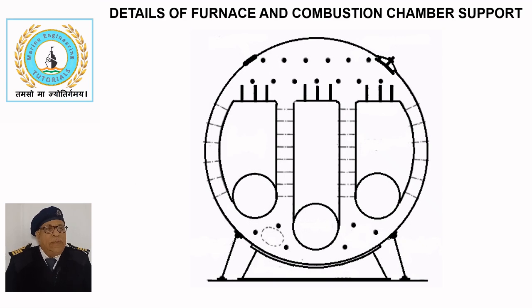Details of furnace and combustion chamber support. Smoke tube boilers are not suitable for high pressure applications because the furnace and combustion chamber are surrounded by water, which exerts significant pressure on their walls.